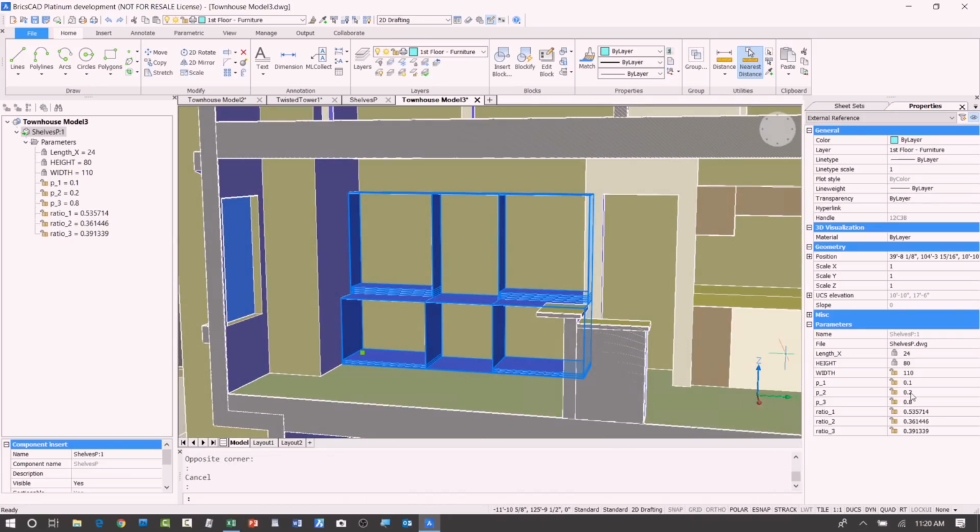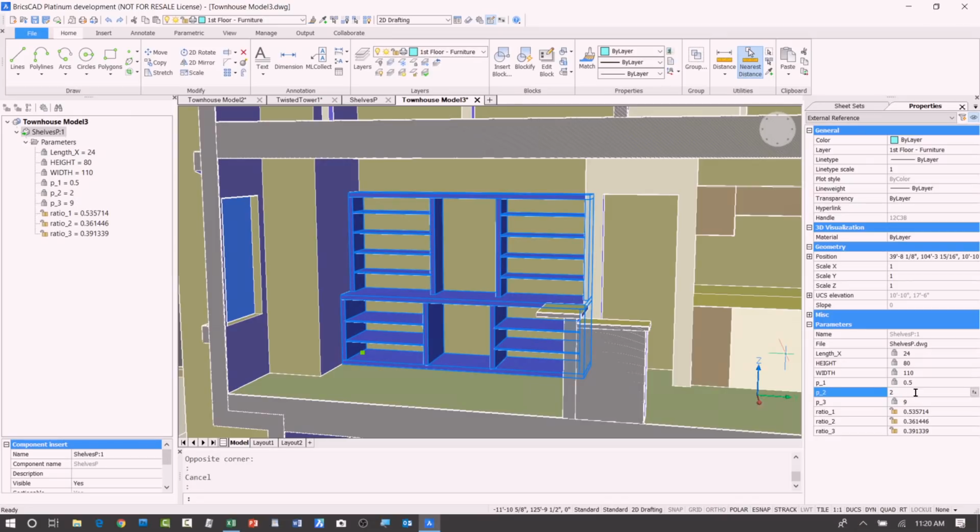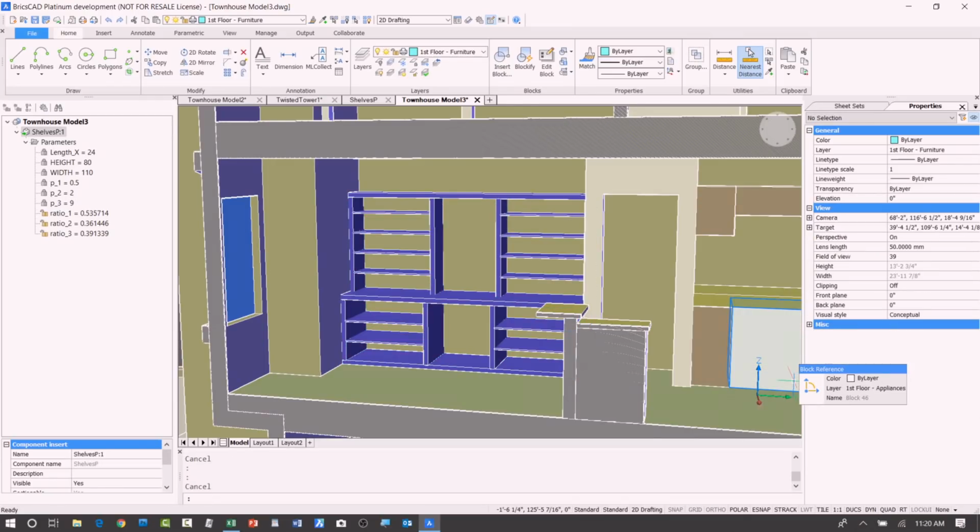And now I'm going to adjust some of these other parameters, like the distance between the shelves. Just that easy, I can start modifying this, and I can change it to be what I want to design without having to remodel anything. I'll change a few more things, maybe make the height of the individual shelves 0.5, half an inch, and then we'll just get really wide here for the other side so you can see the difference. I can go in here as much as I want and change those parameters, and I'm actually changing my design without having to redefine or remodel the geometry. Fun tools.